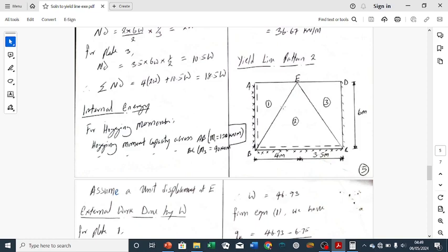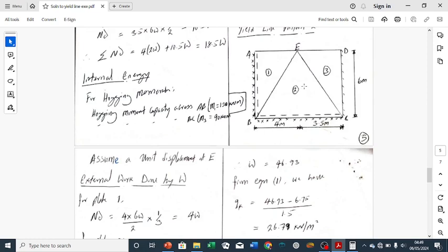It is similar to the first one, it's just that this yield line actually meets with this other yield line. They all meet at this unsupported edge. So once we have this, it is a realistic yield line pattern. You need to spend time and learn how to come up with a realistic yield line pattern.